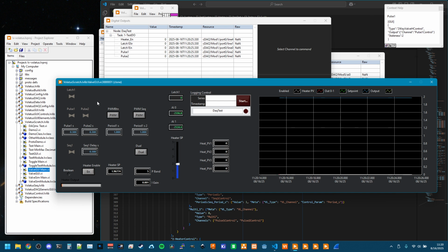So normally with a valve and a control and a GUI, you might click it and it turns on and stays on in that state. You click it again, it closes, stays in that state. However, what if you have valves where you only want them to momentarily go to a state? So you can set up pulse control. And what if you want to change that pulse time?